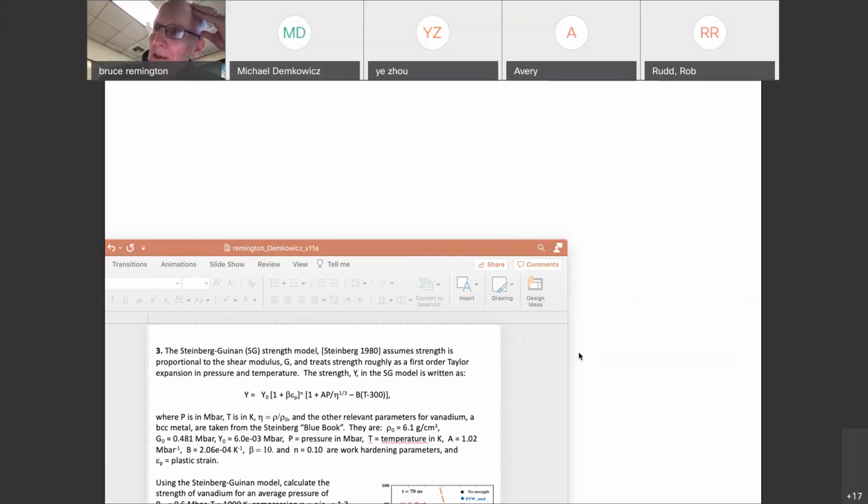Well, let's see. We can certainly measure melting in the sense that with diffraction, you can see the lattice arcs, they go away, and you end up with a very diffuse pattern. So I think we can diagnose melting. The uniaxial compression, we're always having to deal with that. You're pushing in one direction, the lattice squeezes up, and then it transitions to plastic flow, and you get a relaxation of that very odd uniaxial compression. But due to the material strength, it doesn't relax all the way.